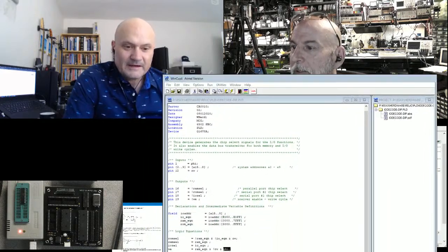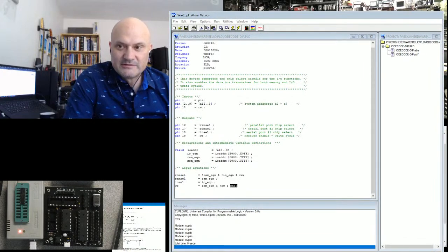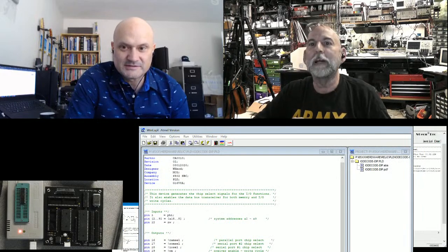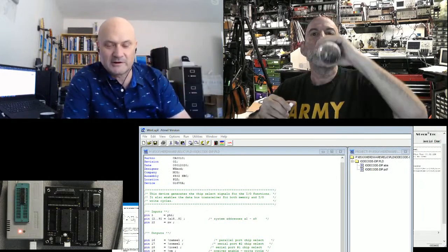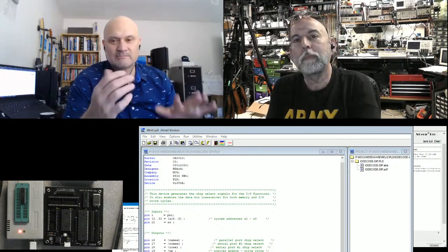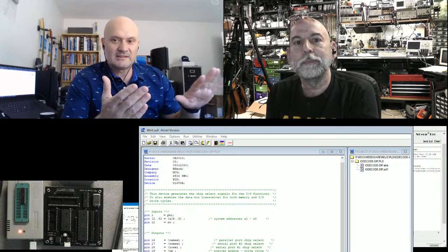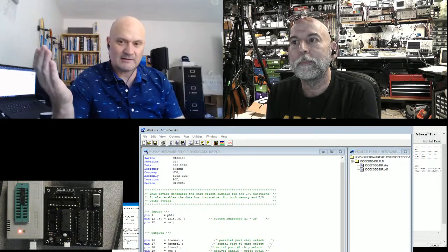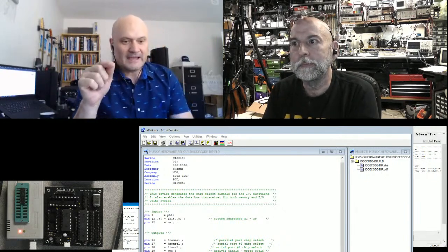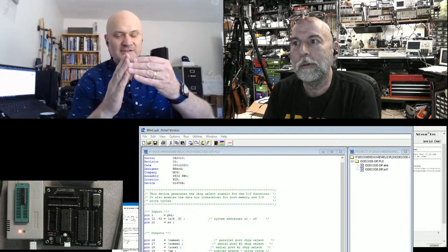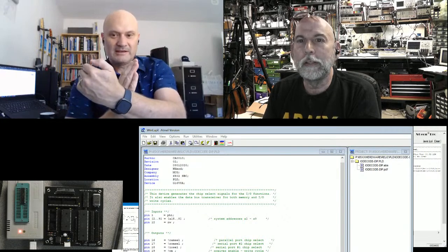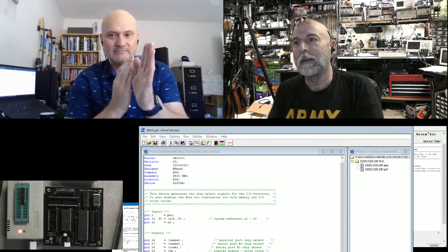Yeah. Now, in an FPGA, you would generally tend to avoid gating clocks. Instead, the whole system is synchronized to a clock, and you have dedicated clock inputs and registers. Maybe that's the difference with the generic array logic features with a flip-flop at the end. You have a clock, and you're using the flip-flop to carry your product term through. You pipeline at an exact moment in time.